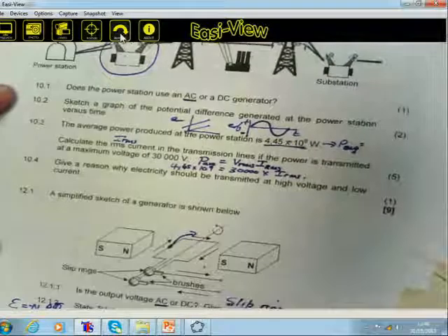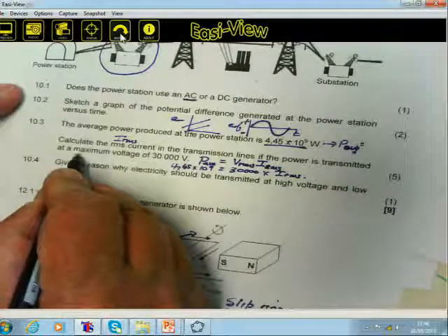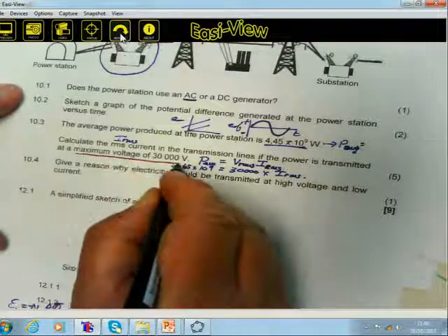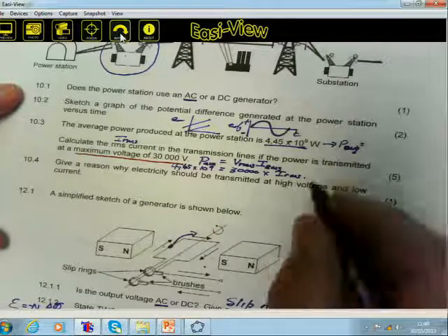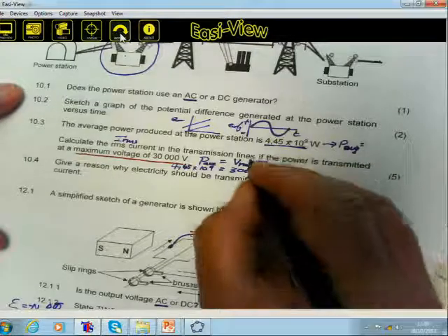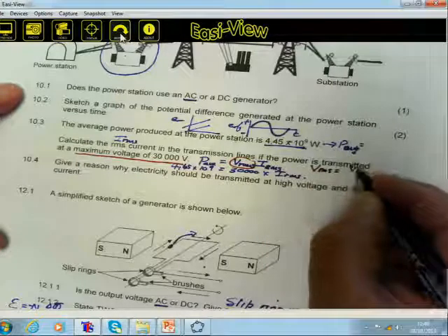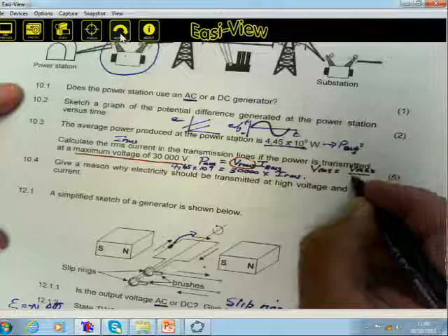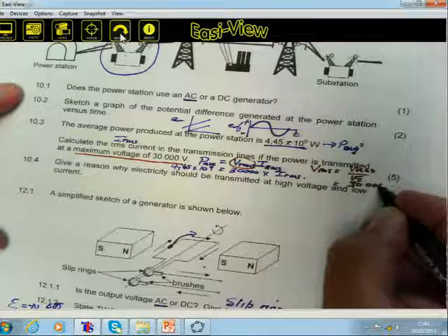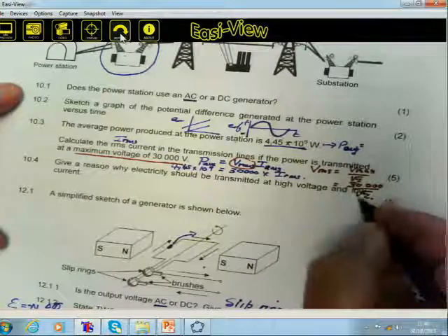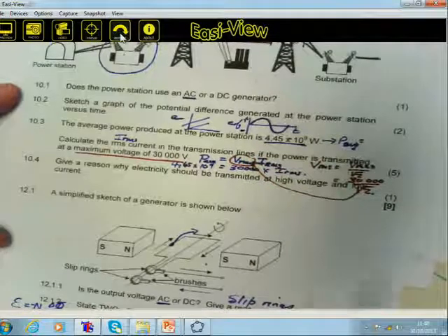Okay. Sempi is correct in this instance. This value here, I misread, it's given as the maximum voltage. So what must we first do? We must first calculate VRMS. First calculate VRMS by means of Vmax over square root 2. And so it will be 30,000 volt divided by square root of 2. And then that value you substitute into this formula, and you use that value for VRMS.